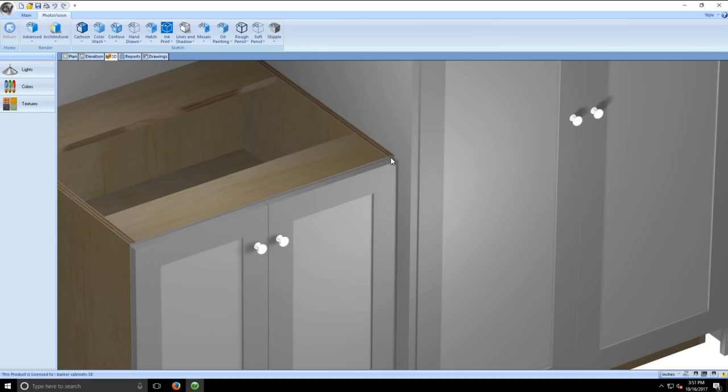If we get into the difference between the 24-inch deep base cabinet, which is our standard, and the 26-inch tall cabinet, imagine there's a countertop on this. It sticks out 1.5 inches. It's a 1/2 inch back from the face there. The countertop now dies off into the side of this finished in panel. Now, what happens if you did 24 inches here and here? That countertop is going to stick out, and there's going to be like a 1/2 inch nub of countertop sticking out to the side there. It's an easy way to get stuff caught on it.